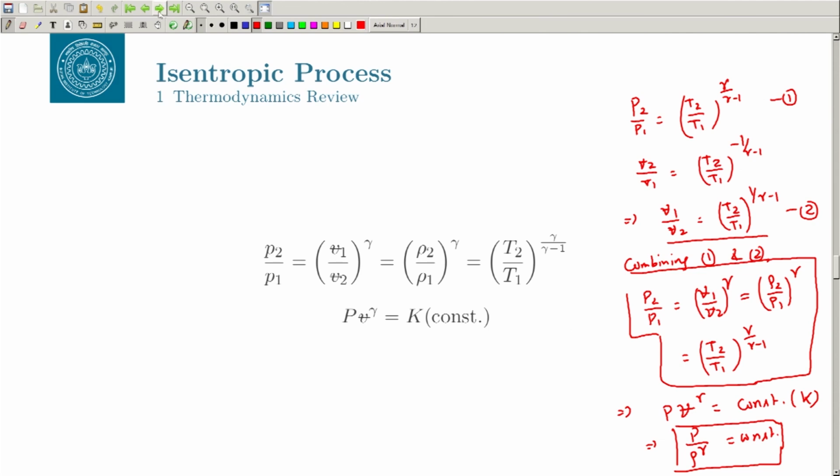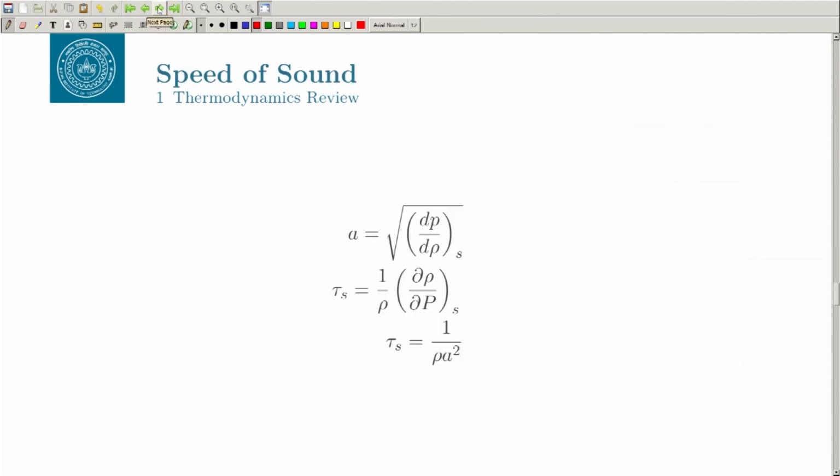So, next, now that we know that, let us find out some of the things that we already know. One is the speed of sound. So, what is the speed of sound? When we speak, waves travel, and you can find out at what speed the wave is traveling. You can consider a system on the left of the wave and on the right of the wave, and use mass conservation and the momentum conservation.